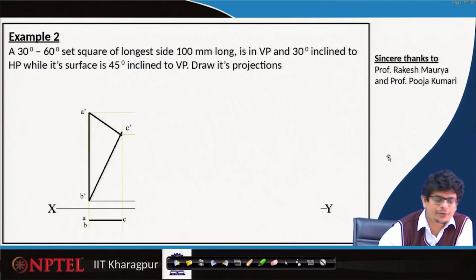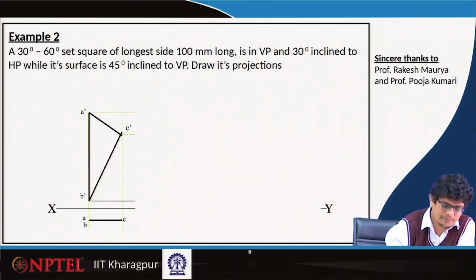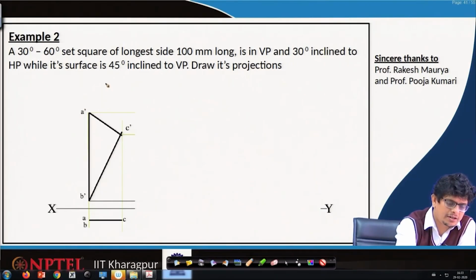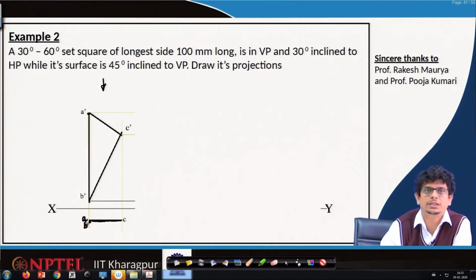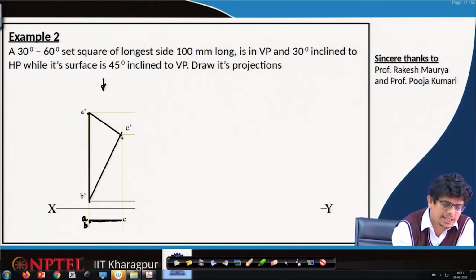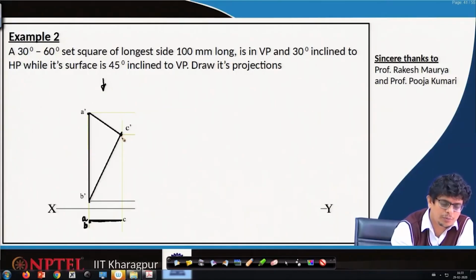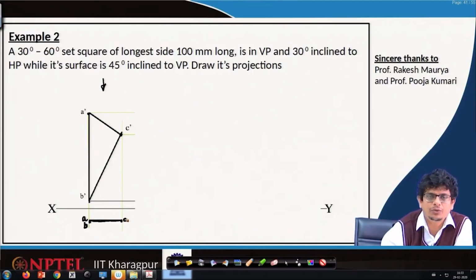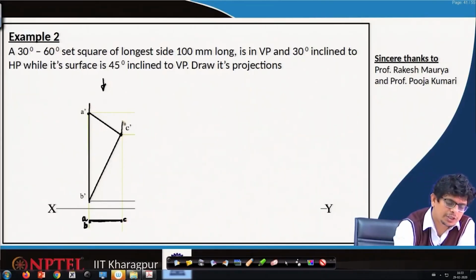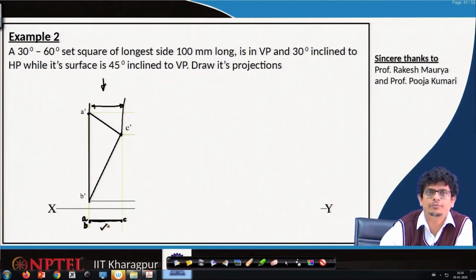If we look from the top view, the frontal plane looks like a very thin strip, where A and B coincide at the A and B points. Similarly, this C point, C prime, whatever we look at in the front view, is projected all the way to C. So, the actual length that we are going to see is this projected length, that is, we are going to see it in the top view.